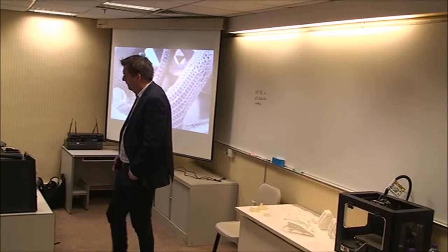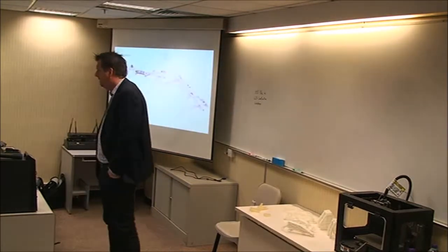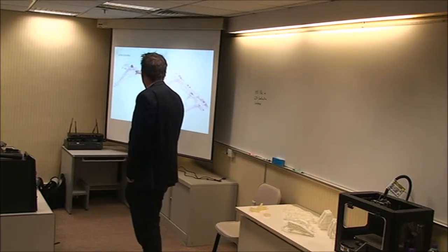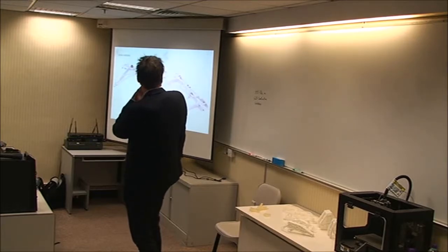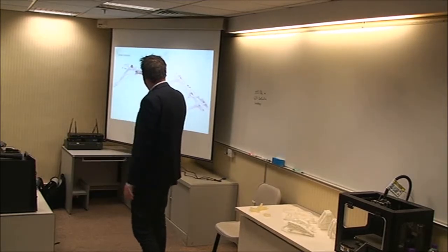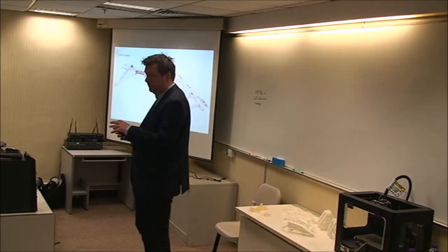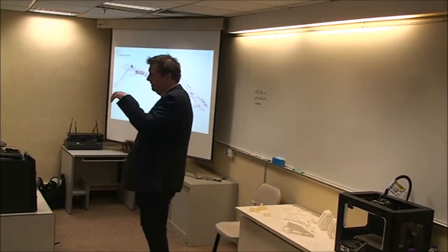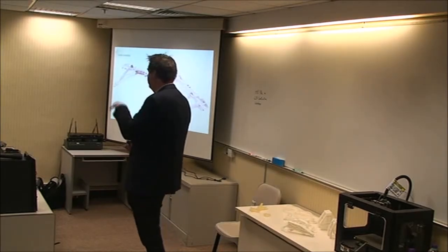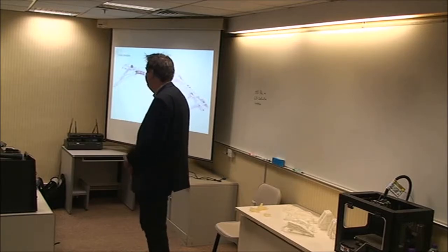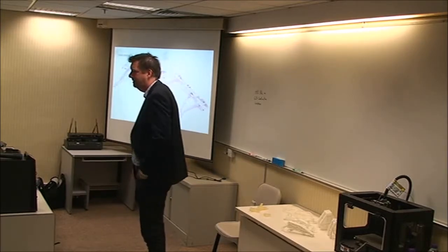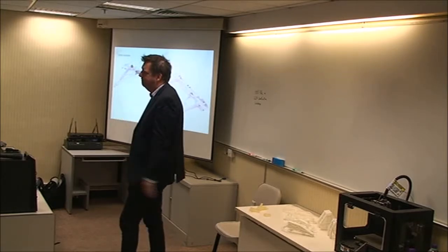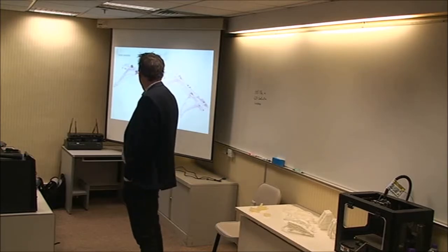Now I've got more lattice coming up. This is called a cross member. It's just a bit of a design study. One of them, the one on the left, has no manufacturing constraints. So it's hollow, could be 3D printed in theory. The one on the right uses a draw direction, so it could be cast. The weight difference between those is about 20% for the same performance. So again, if you can 3D print something, you'll get better performance than using traditional methods.